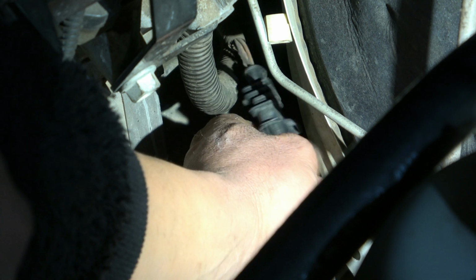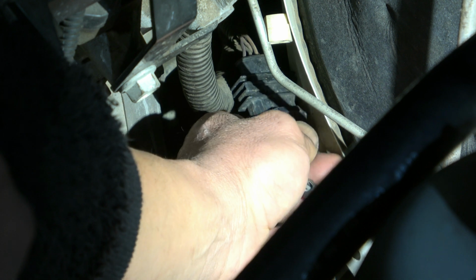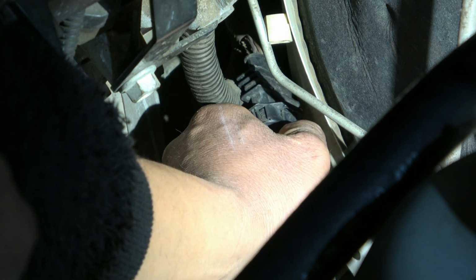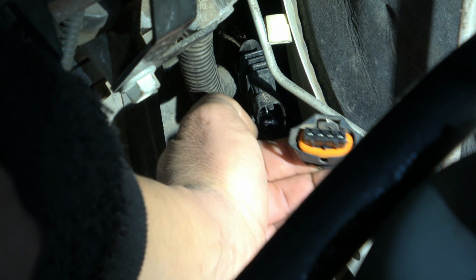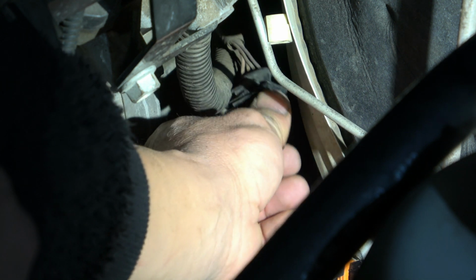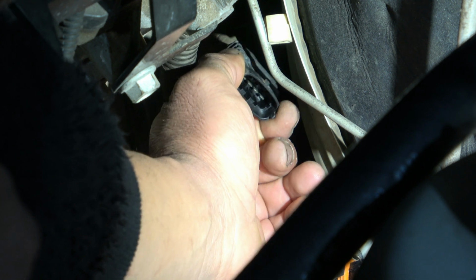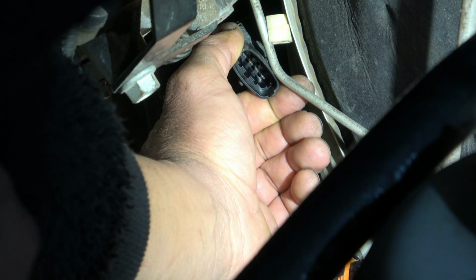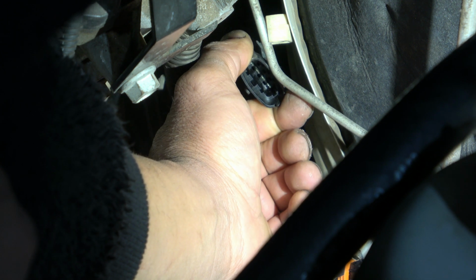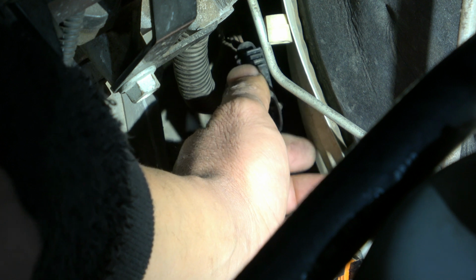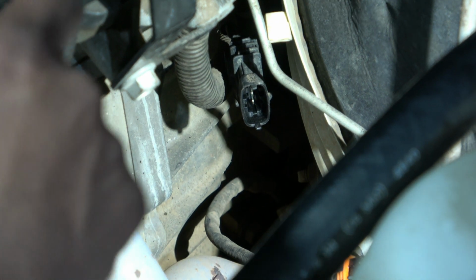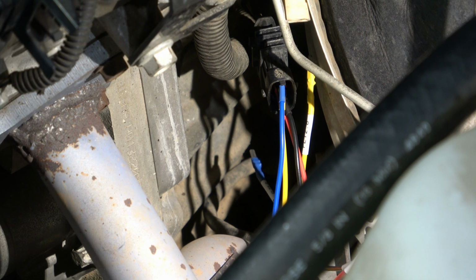So what we need to do is disconnect this wire connector. I'm not too worried about the oxygen sensor side itself. I'm just going to focus on the harness going towards the engine, this harness right here. To make it easy, I might put some extension there so we can bring it up a little bit and do more testing easily. I'm just using the breakout lead, so I have to make sure I don't short circuit any of these wires. This one, I'm just going to grab my test light.